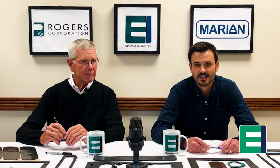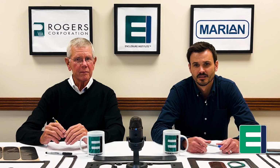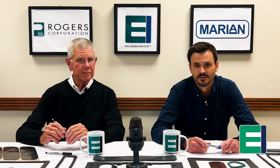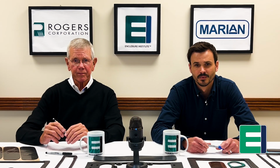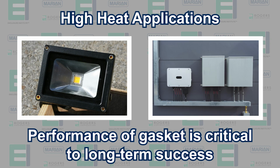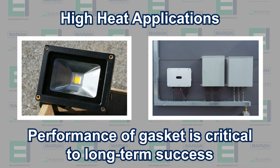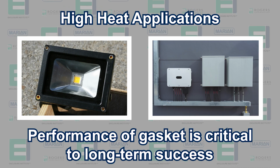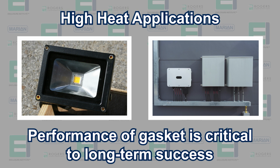As oxidation of the gasket material progresses, it will accelerate stress relaxation and compression set. If your device and gasket are subject to the environment where oxidation flourishes, and your device is intended to function for a medium or long term, you will want to choose a material that is less susceptible to that chemical breakdown. For example, this would be true in high heat environments, like lighting enclosures and power inverters, where the performance of the gasket is critical to the long-term function of the enclosure it protects.